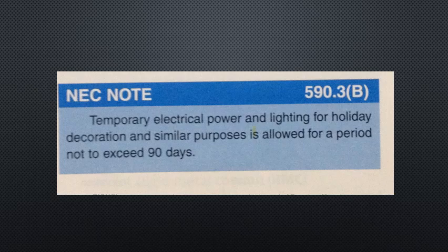And fourth, regularly scheduled maintenance checks will be performed on equipment grounding conductors. The checks will be performed at no more than 3-month intervals and will verify continuity, any damaged condition, and proper polarity relative to the grounding electrode conductor.